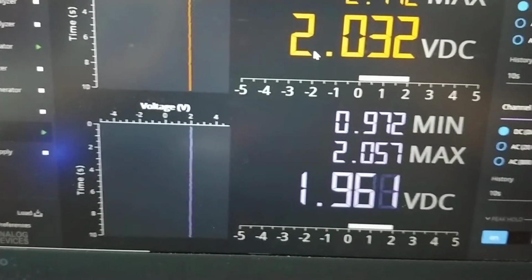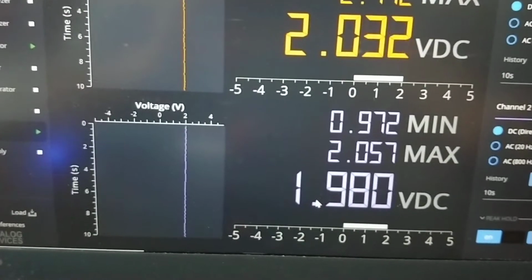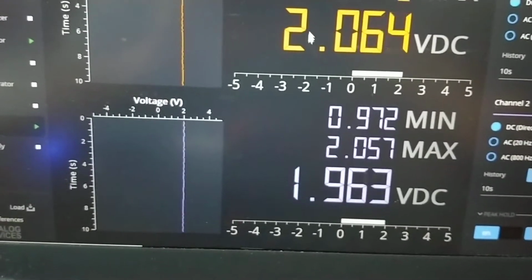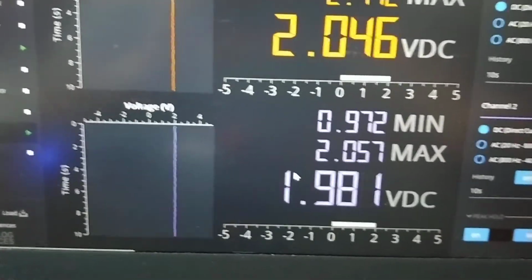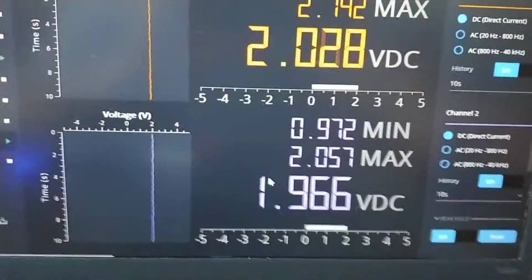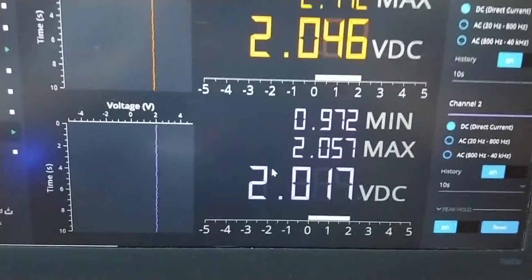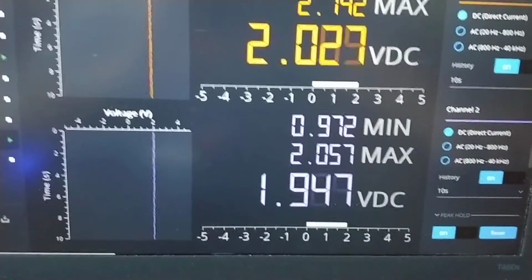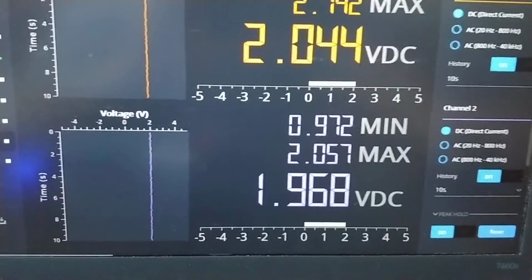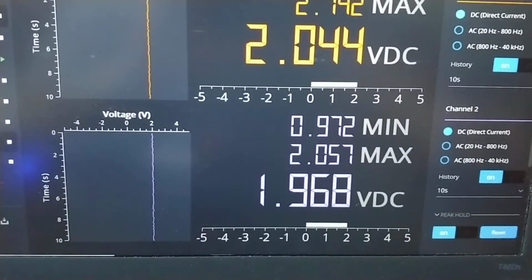But we sum this up, right? And where's the missing voltage? Because if we put in 5, why am I only having 2 and 2? Well, that's across the 50 ohm series resistance, which we talked about in the LTspice prior video. All right, let's go look at this in the XY domain.